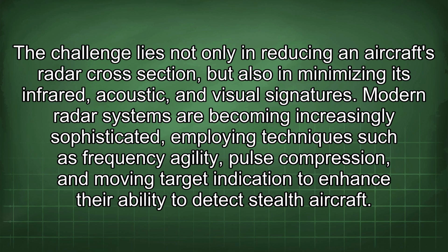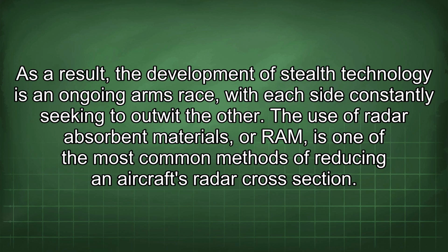Modern radar systems are becoming increasingly sophisticated, employing techniques such as frequency agility, pulse compression, and moving target indication to enhance their ability to detect stealth aircraft. As a result, the development of stealth technology is an ongoing arms race, with each side constantly seeking to outwit the other. The use of radar absorbent materials, or RAM, is one of the most common methods of reducing an